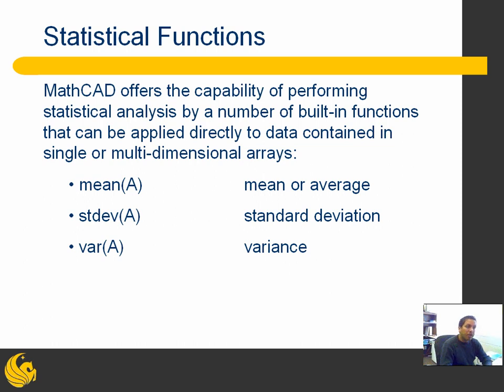MathCAD offers the capability of performing statistical analysis by a number of built-in functions that can be applied directly to data contained in single or multidimensional arrays. For example, the three basic statistical functions, the mean value or average, standard deviation, and variance, you can calculate directly using these functions. So let's go straight into MathCAD and put these concepts in practice.